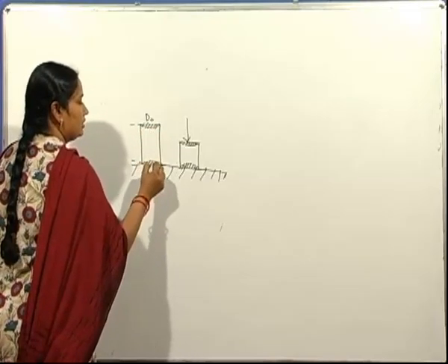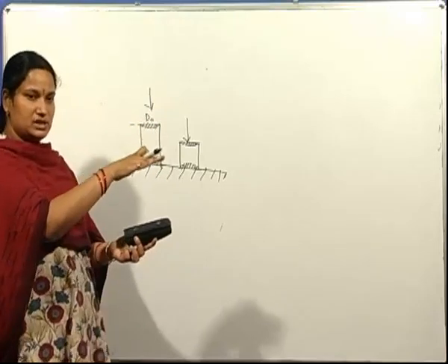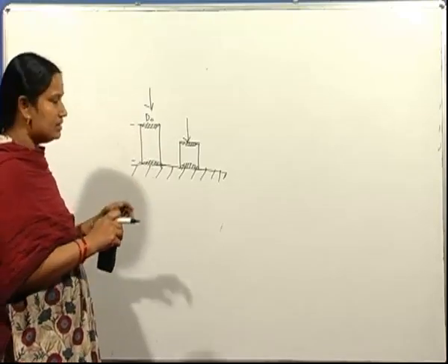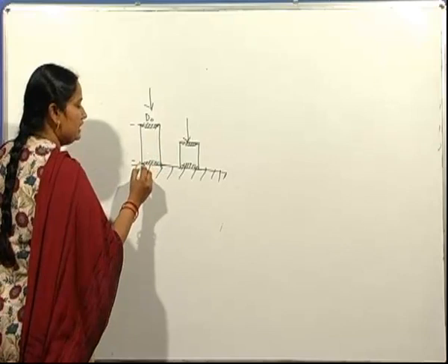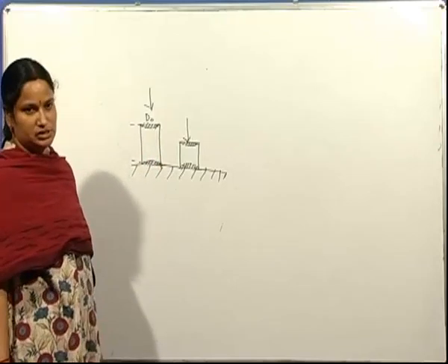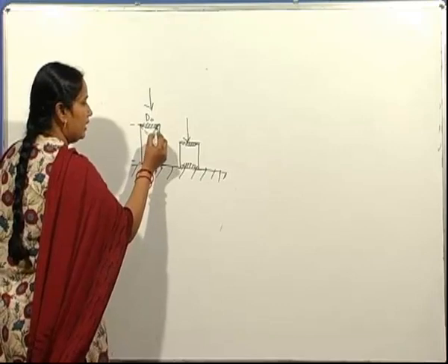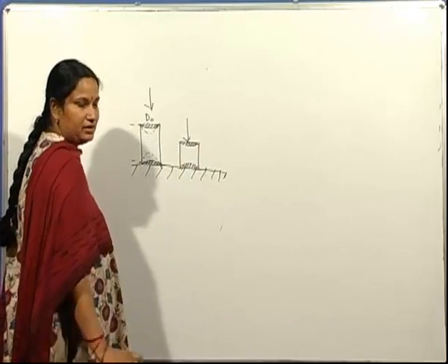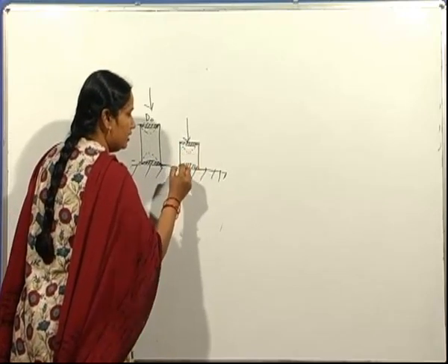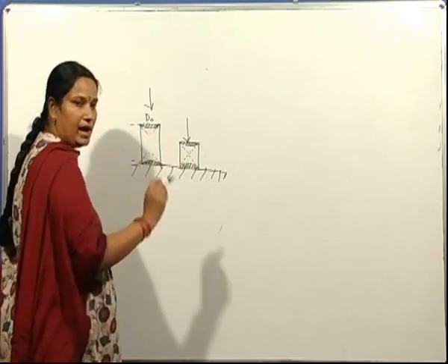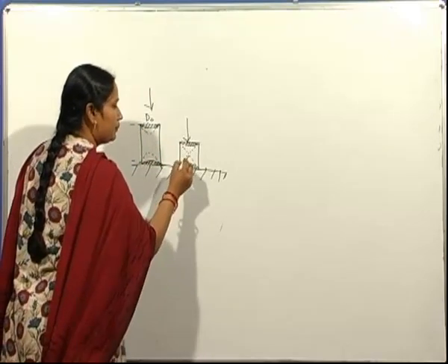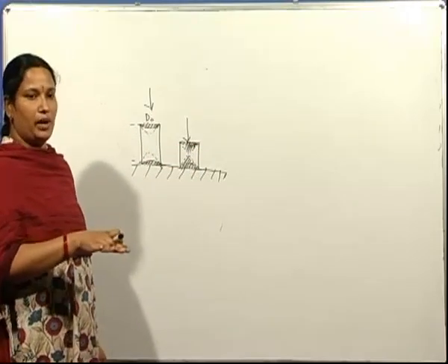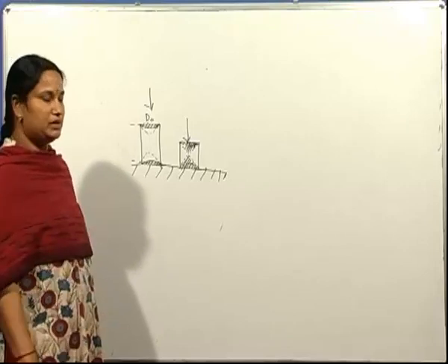So as the compressive force is applied on the specimen and reduction in height occurs, these hatched regions, which indicate the undeformed regions, approach each other because of the friction. For the case of shorter specimen, more is the undeformed region. These two hatched regions overlap. Thereby more is the undeformed region, so more load or more force is required to deform the material.